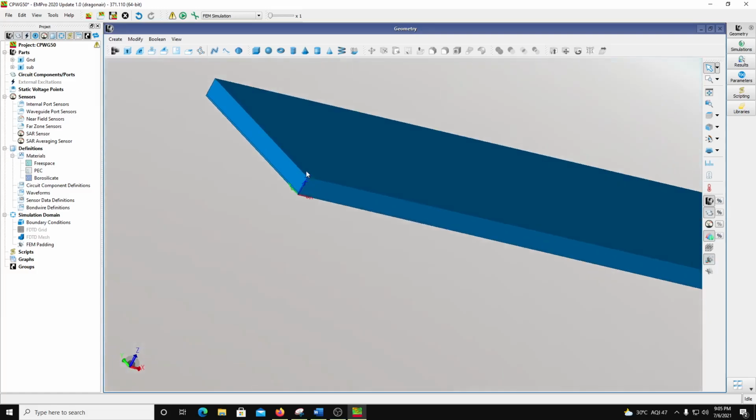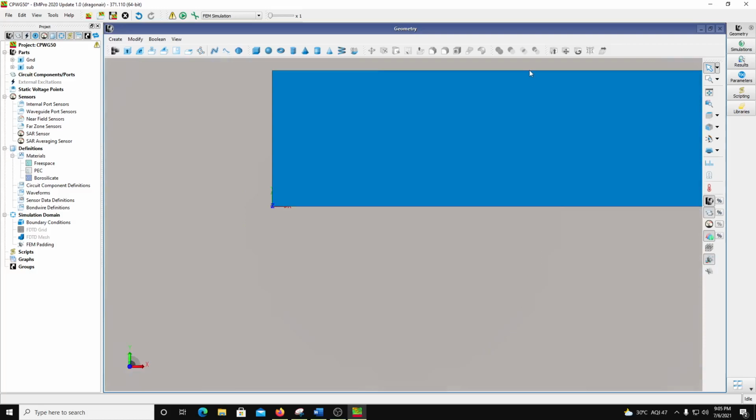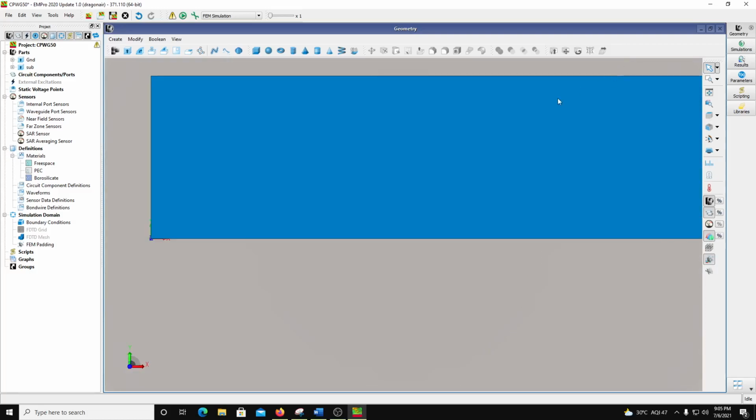Next thing is I'm going to draw the vias. Now here you have to have a certain calculator in your mind. So if I go from here 0.4 micron, that would be the edge, right? And that means I have to go right by 0.1 and down by 0.1, so that will be like 0.3 over here, and on the height 0.3 and 0.1 on the width side.